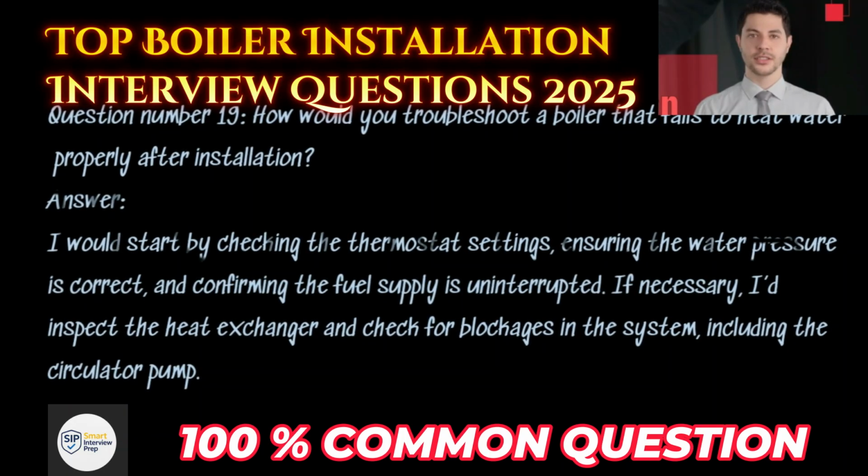Question number 19. How would you troubleshoot a boiler that fails to heat water properly after installation? Answer. I would start by checking the thermostat settings, ensuring the water pressure is correct, and confirming the fuel supply is uninterrupted. If necessary, I'd inspect the heat exchanger and check for blockages in the system, including the circulator pump.